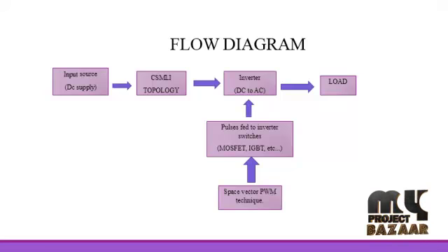This topology is developed to overcome the disadvantages of the conventional topology. In the developed cascaded topology, the voltage values and corresponding switching states are shown. This inverter is able to generate all voltage levels, except that it needs an additional DC voltage source and 2 unidirectional switches connected in series with the cascade topology. The developed cascaded inverter generates all the levels; power switches S1 and S2 and a DC voltage source are used to produce the lowest output level. The amplitude of this DC voltage source is equal to the minimum output level. The number of power switches is equal to the number of IGBT power diodes and driver circuits.